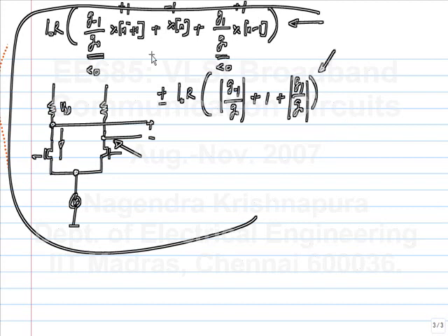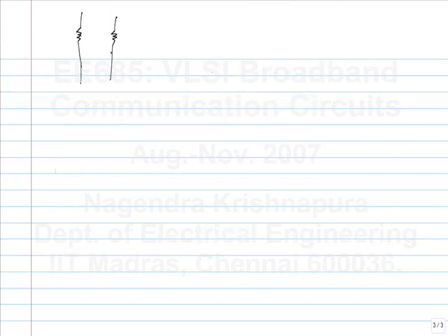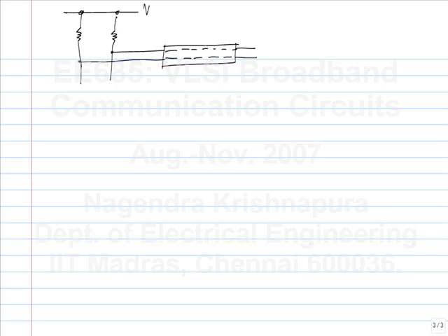What else was here? Next thing is, how do you connect it to the transmission line, and that has some implications on the swing as well. So let's say we have the driver on this. I won't show the transistor level circuit. It's connected to a differential transmission line. A differential transmission line for our purposes now is just a pair of wires. So there is a wire here and another wire here, and you have termination on the other side as well.